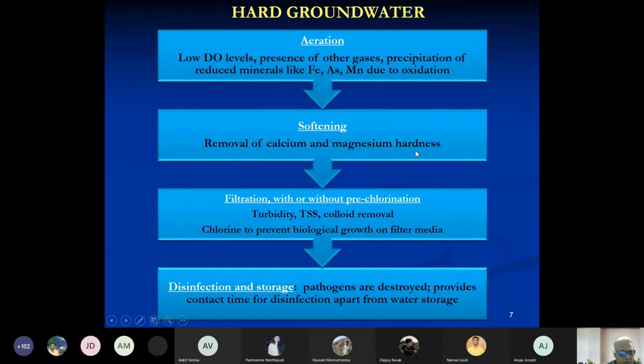If the water contains high amounts of calcium and magnesium, it's not going to froth for various reasons. And you will often find in very hard waters that the soap, when you try to use it, forms what is called a white curd-like precipitate. These are all indicators of high concentrations of calcium and magnesium. That is one very obvious problem associated with hardness.